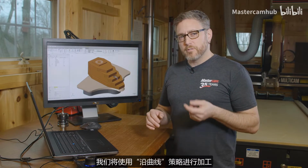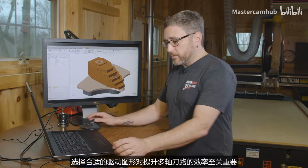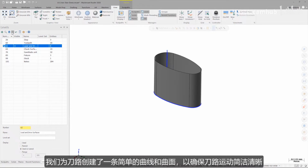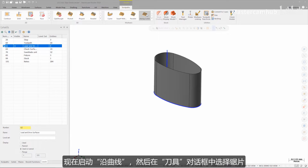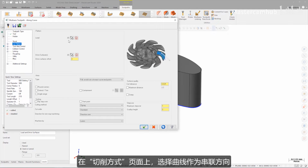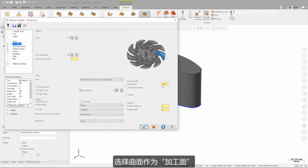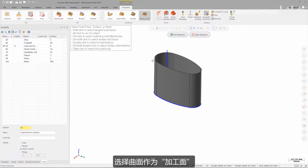An efficient multi-axis toolpath starts with having good drive geometry. Since we'll be using a multi-axis toolpath for this operation, we've created a simple line and surface for the toolpath to follow to ensure that the toolpath motion is clean. We'll now launch a long curve, and on the Tool tab, select the saw. On the Cut Parameters page, select the line as the chain for the lead and the surfaces as the drive surfaces.